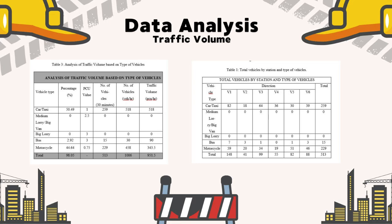Based on Table 3, cars and taxis made up 50.49% of the total traffic and contributed 518 PCU per hour. Motorcycles accounted for 44.64%, contributing 343.5 PCU per hour, while buses contribute 90 PCU per hour. Overall, the traffic volume was 1,006 vehicles per hour, or 951.5 PCU per hour. This shows that the traffic at the study area is mainly dominated by cars, taxis, and motorcycles with very few heavy vehicles.